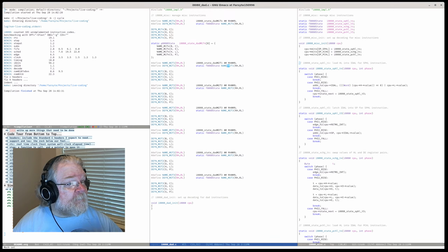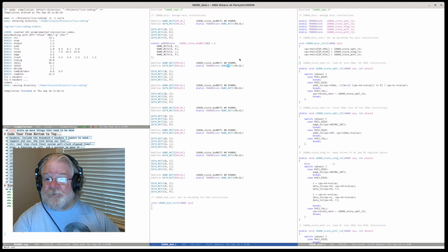M2T1, if we look at DAD, make sure I've got that here on my screen. M2T1 reads the low register. M2T2 is going to set up the ALU input from the L register and temp and form the ALU output. M2T3 stores the low and arranges for M3. So yes, all those little bits of stuff do indeed get needed.